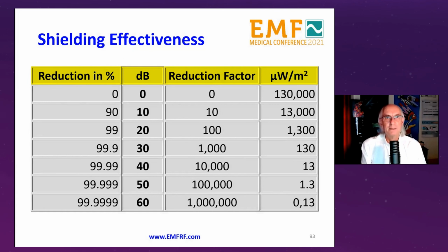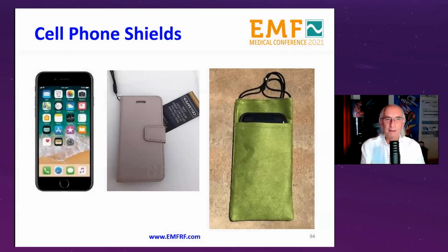Why? Because you've got openings, you've got windows, you've got doors, you've got chimneys, you've got vent pipes, you've got cracks and crevices and so on. So whatever it lists on your material data sheet is not necessarily what you're going to get when you install it. So that's where the measurements before and after come in handy.